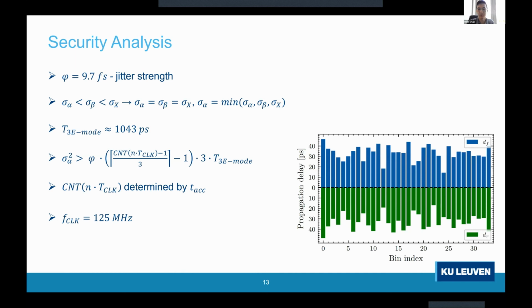The thing is that I presented a simplified version here. Indeed, I have a simple bubble detection in the pulse width encoder that detects when there is a bubble and does not output the bit. Because the bubbles appear very rarely, my technique is to use this with a validity signal. When a bubble is detected, that bit is not output, but that does not occur often, so it does not influence the throughput significantly.